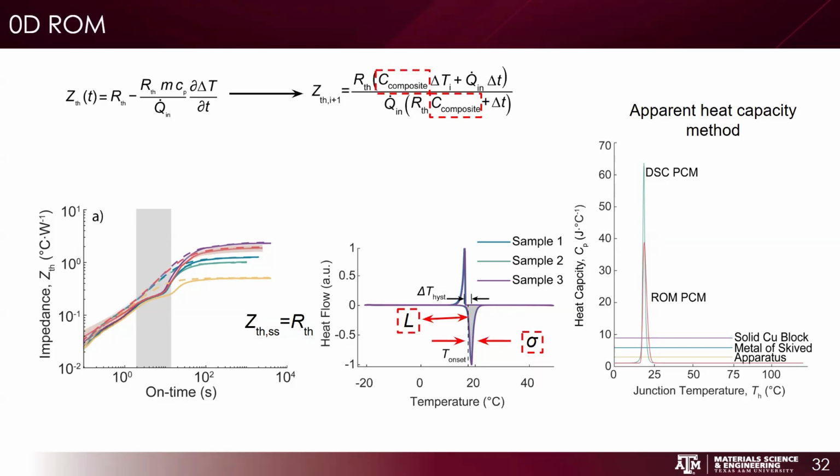Well, I think the original question was, is it congruent melting? So first, let's just answer that. Does it melt congruently? What's the definition of congruent? Does that mean the melting temperature is fixed, irrespective of scanning rate? Yeah, it just means that the solidus and the liquidus are the same temperature. There is no mushy zone. I guess I would say yes for this system, it's congruent melting.